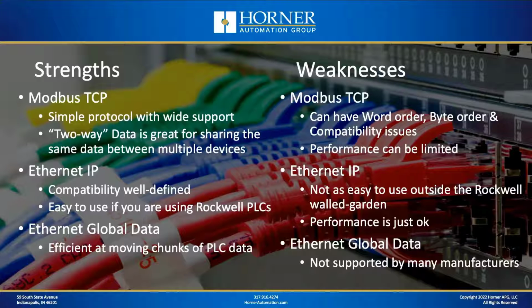Next, let's talk about Ethernet global data, that third protocol that I'm talking about today. The Ethernet global data is really good at one thing, and that is it's very efficient at moving big chunks of PLC variable data. So if you have a few hundred words of variables that you want to move from controller to controller, Ethernet global data does that extremely well.